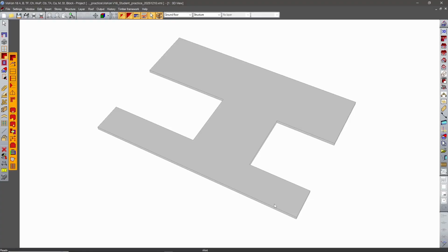Let's start with 2 dual pitches on these 2 longer sides. So you start with the command dual opposite pitches, and this time we're gonna use the points creation mode because I want to define this whole side as one edge of the roof, but this middle portion comes in between the 2 ends, so I cannot just simply choose this edge because this ends here.